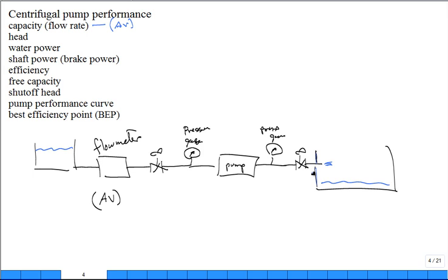It's the same flow rate, right? The volumetric flow rate's the same. It's incompressible, it's liquid water, mass density is constant, volumetric flow rate is also constant. We talk about the head, lowercase h in units of meters. We could talk about cap H in kilojoules per kilogram, or we could talk about the pressure head in kilopascals. All three units are good measures, right?